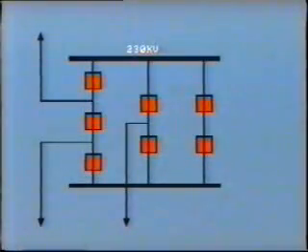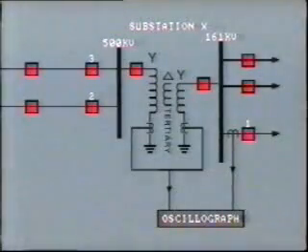Protective relays and breakers operate extremely fast. They can clear a fault in just a fraction of a second. Unless we can capture fault data and reconstruct what happened during that very short time frame, we would probably never be able to pinpoint the cause of relay or breaker misoperation. Furthermore, even if the protection seems to operate correctly, there could be problems that would go unnoticed if an after-the-fact analysis is not conducted. Here's an example that shows why every fault on the system should be investigated.